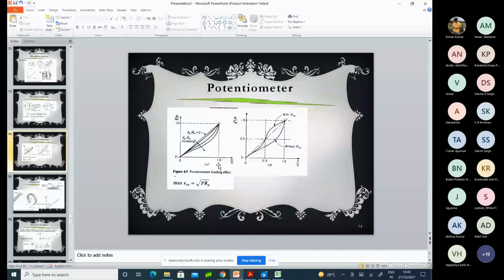All those things are about the static characteristics. About dynamic characteristics, this is a zeroth order instrument, so whatever input you give, the output will follow directly. But if you want to measure E0 with a voltmeter, and that voltmeter is a second order instrument, your overall measurement will become a second order measurement system.